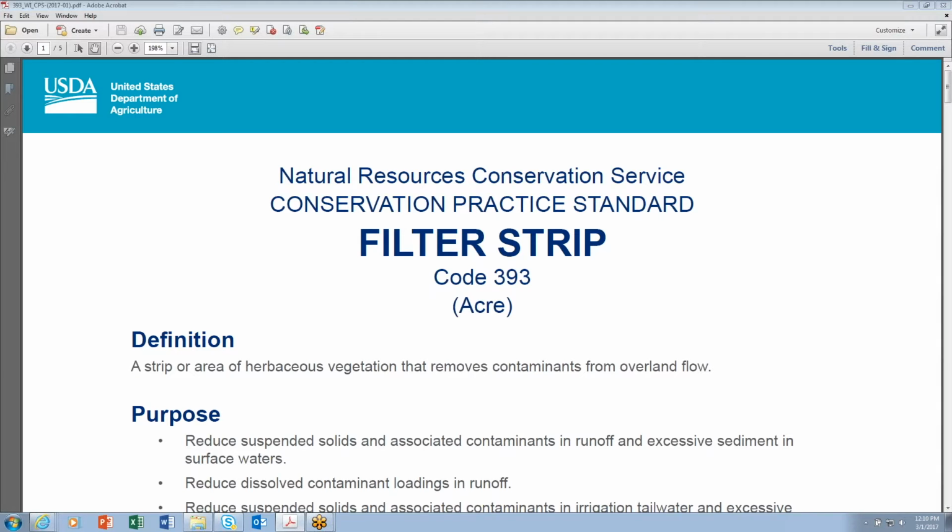And that's absolutely true. A filter strip, just like a grass waterway, needs to have a 10-year life. That's what it's designed to do. So if you're sedimenting in quicker than that, then you're not going to get the full use of a filter strip. So you need to deal with that. That being said, I know a couple of folks that sat on the SOC committee chatted with me, and I know that I spent quite a bit of time saying, what is that minimum width? And what is the formula telling us? And what's the math saying?